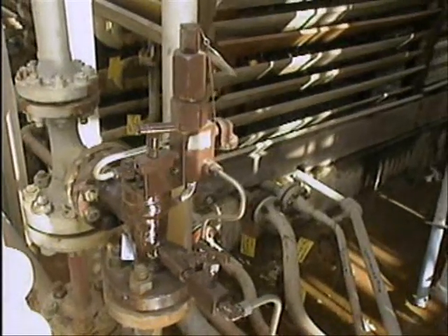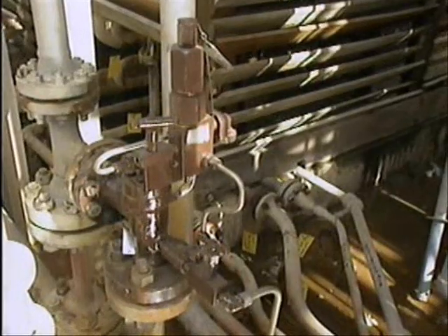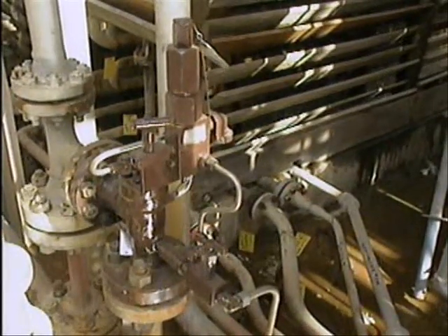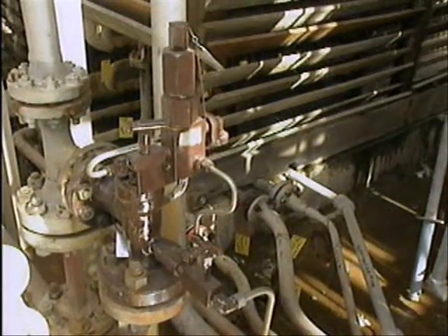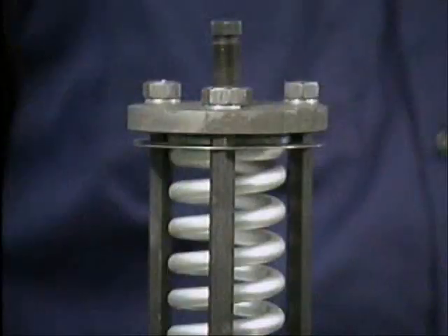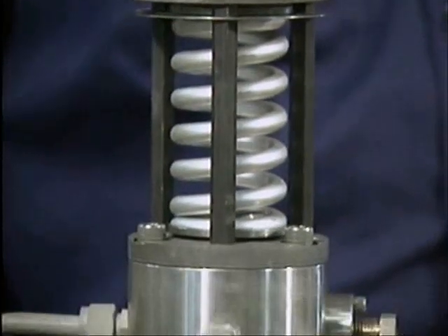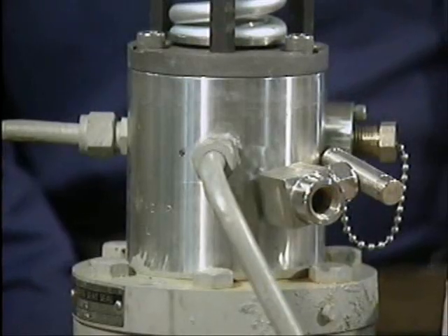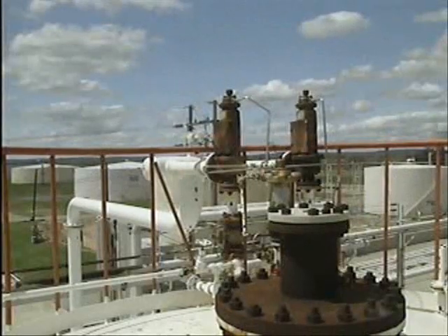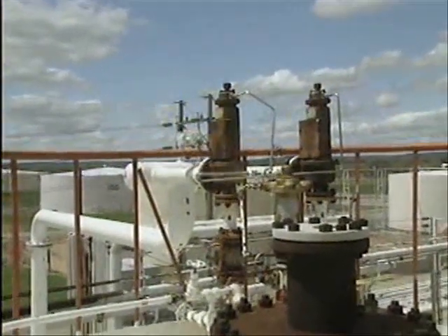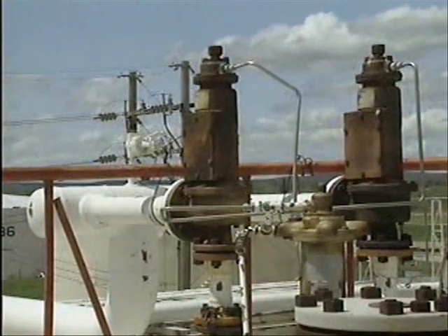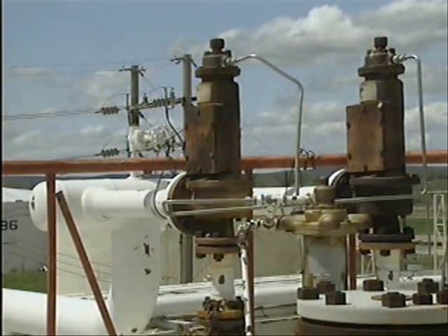Pilot-actuated relief valves operate much like safety valves. That is, they pop open rather than open gradually, and they have a predetermined amount of blowdown to prevent chattering. However, a pilot-actuated relief valve also has a separate pilot device that senses excess pressure conditions and causes the valve to open. This arrangement allows excess pressure to be detected in one part of a system, such as a steam line, while the valve protects another part of the system, such as the boiler.